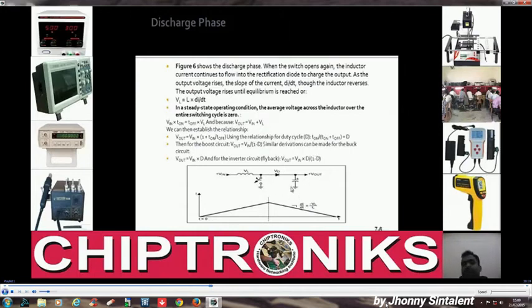And when we study the notebook schematics, we'll see this switch and this diode replaced by two MOSFETs, the upper side MOSFET and the lower side MOSFET. We are just understanding the basic concepts behind the regulators, and we'll use it to understand the datasheet of the regulator IC.